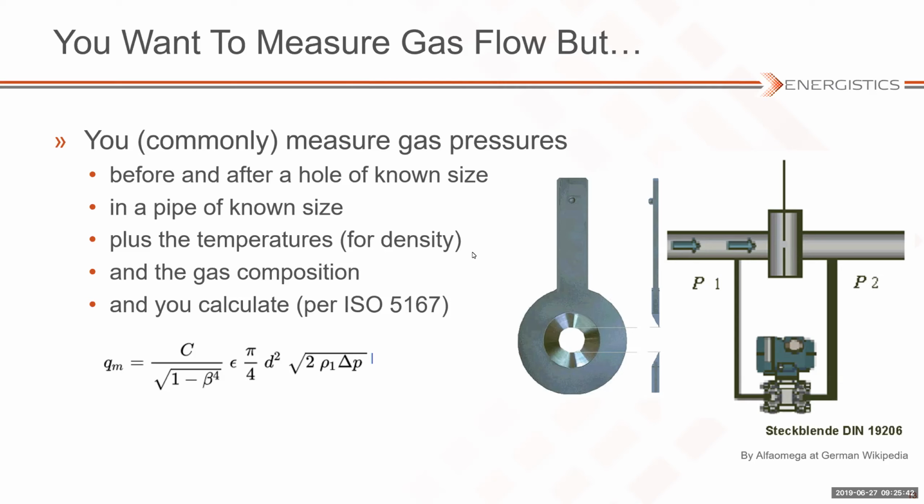So that seems like adding a lot of data to the task of data management, but the truth is, if the wrong equation was used, so if the ISO 5167 equation wasn't applicable, let's say, for example, it's extremely cold outside, that equation might not be applicable. So data managing that information so that a data analyst can calculate what the flow rate actually was rather than what was reported out of the flow meter will enable them to be able to use the data.